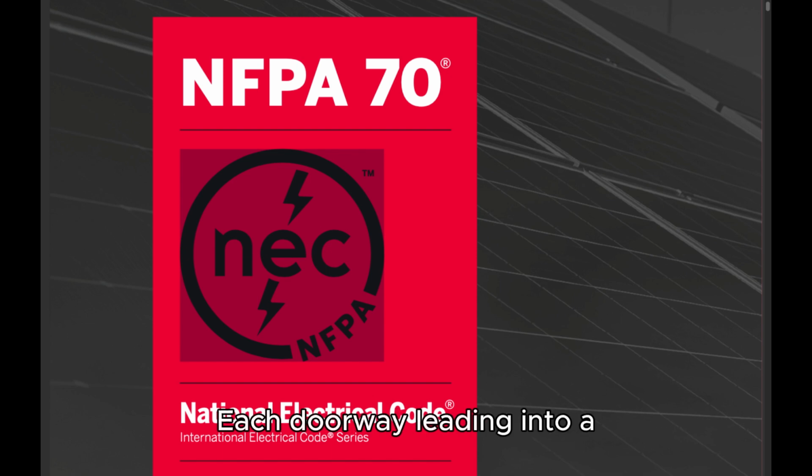Each doorway leading into a vault from the building interior shall be provided with a tight-fitting door that has a minimum fire rating of 3 hours. The authority having jurisdiction shall be permitted to require such a door for an exterior wall opening where conditions warrant. Exception to 1, 2, and 3: Where the vault is protected with automatic sprinkler, water spray, carbon dioxide, or halon, construction with a 1-hour rating shall be permitted.